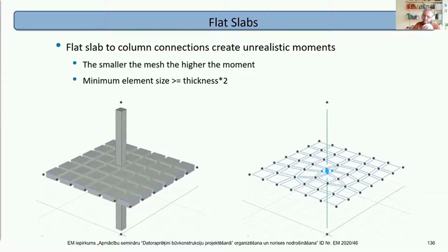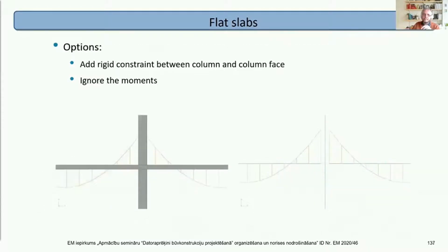But anyway, so we can add in offsets to prevent the slabs actually touching the column. We're stopping at the column face, or we can say, actually, the bending moment within the column, it's not real, so we just ignore it. Yeah, the bending moment actually peaks up here somewhere, but it's not a real value. We just stop the bending moment calculation. We just ignore the bending calculation in this perimeter and go with that value.